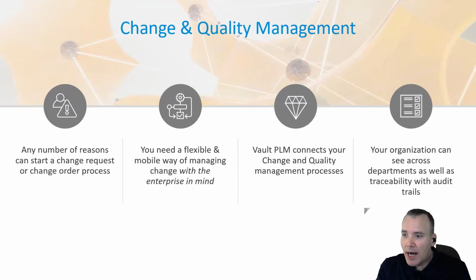So another question, can I link items in CAPAs or ECOs or ECRs in Fusion Lifecycle to items in Vault? Absolutely. So that's a key part of the interconnection, is you have an item in your Vault item master that essentially has a direct equivalent to the items and BOMs workspace in Fusion Lifecycle. And the connection between the two can keep those in sync. New items created in Vault can be pushed up to Fusion Lifecycle. Revision levels, statuses can all be managed that way. So there is a one-to-one correlation generally between the two in terms of their item masters.